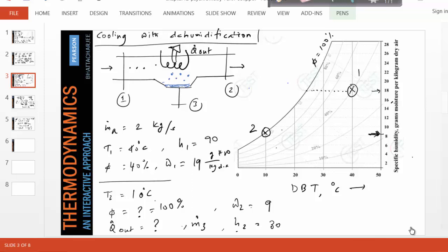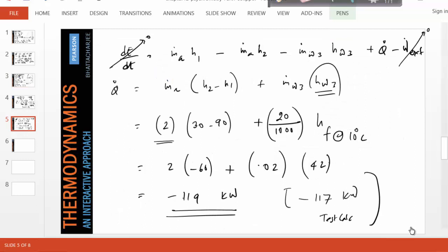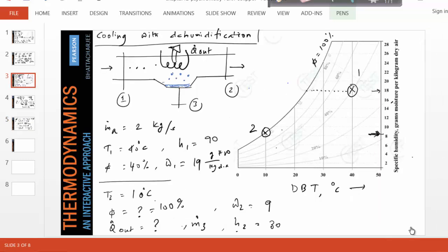Remember while we did the heating, we found that if we go half the way, the heating requirement goes down by 50%. We want to know here the cooling requirement. Notice it is 117, does the demand decrease by half? In other words, suppose you find outside air to be at 40 degrees and you want to cool your room down to 10 degrees Celsius, and you're paying for it by removing heat at a rate of 117 kilowatt. Question is, if you can live with half the way, say 25 degrees Celsius, what's your saving? Do you save 50% of energy or more?